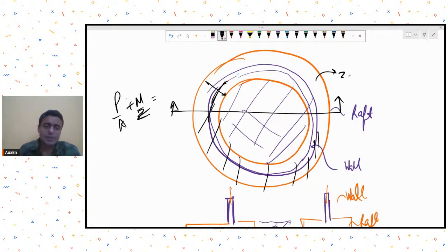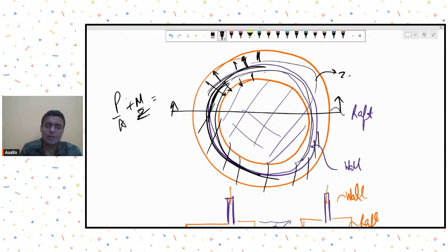Now, in this case, because in annular rafts, we will also usually provide a strap beam like this. That strap beam may be in the form of a wall or maybe in the form of an actual rigid element. What we are effectively able to do is have the bending of this annular raft only in one direction, that is along the width of this raft.